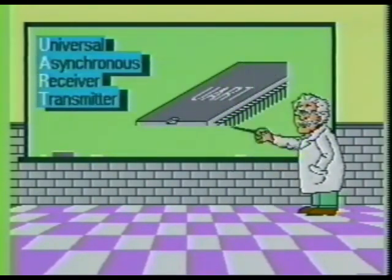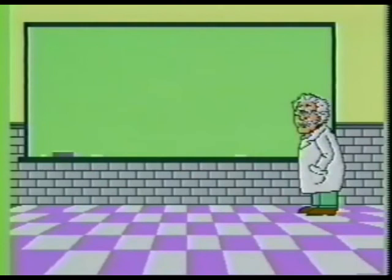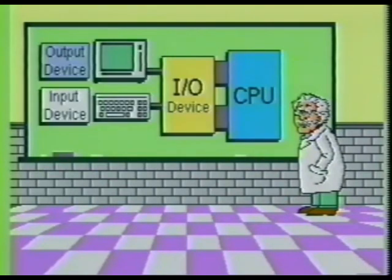The Universal Asynchronous Receiver Transmitter IC is a common serial I/O device. It is capable of receiving and transmitting data information in serial form to connecting peripheral devices. The serial information received is converted into parallel information before it is directed to the processor. In the same respect, the processor sends parallel data to the I/O device, where it is converted into a serial format before it is transmitted to the peripheral device.